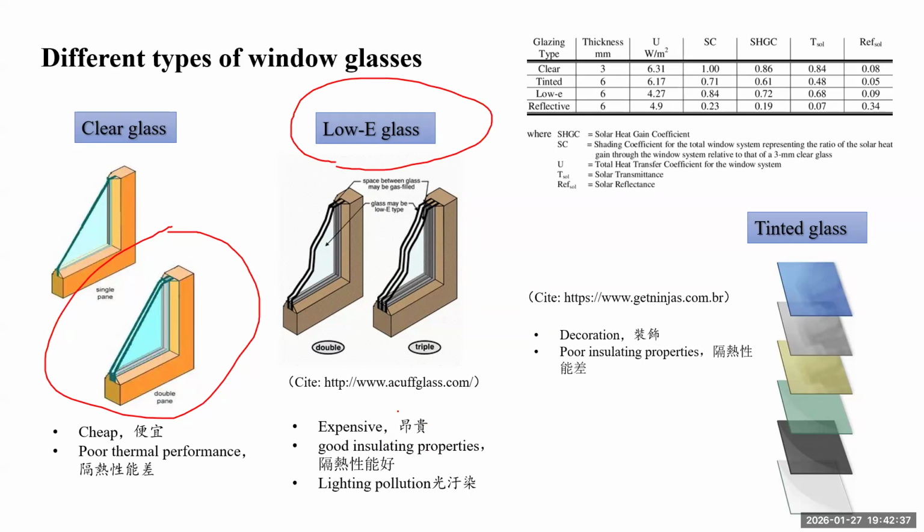But there are several types of low E coatings, for southern cities and for northern cities, and they have drawbacks. The low E coating with high reflectance may cause light pollution for the surrounding environment and also for the interior. Due to its low emissivity, it also traps heat, especially the heat leaving the space.